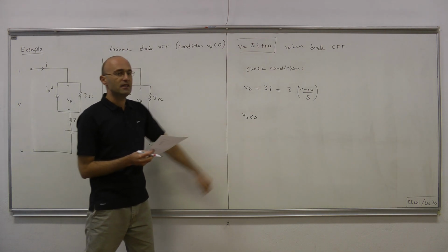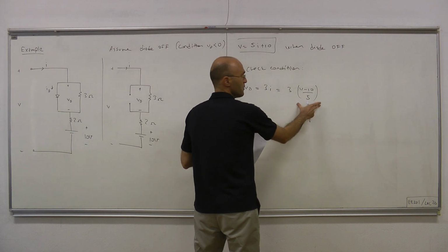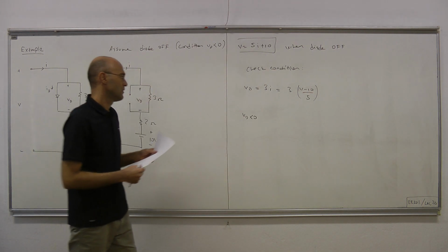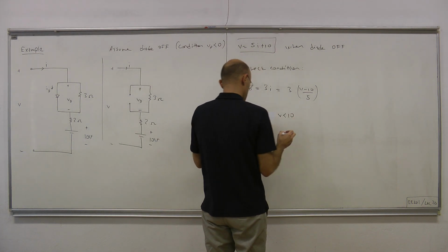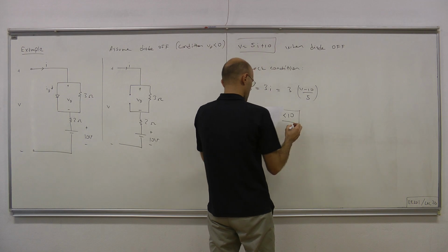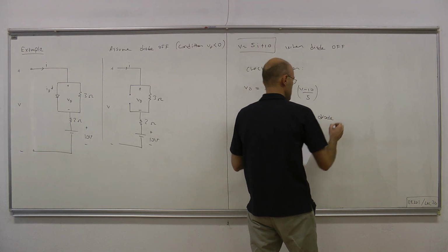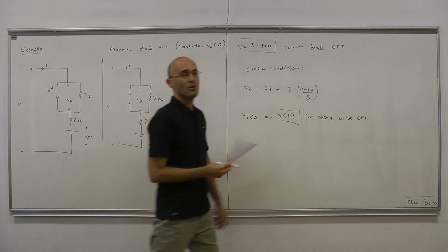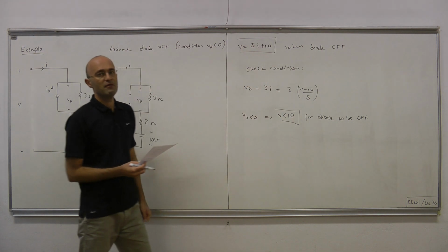Okay, so VD negative implies that this thing here is negative, and it means that V must be less than 10. Okay, V is less than 10 for the diode to be off. Okay. So when V is less than 10, that's the IV relationship.